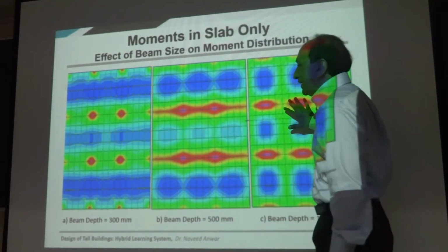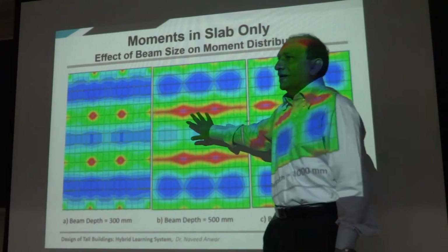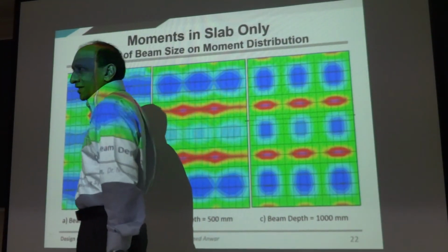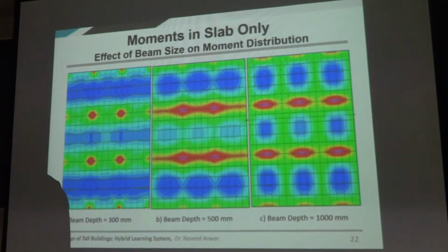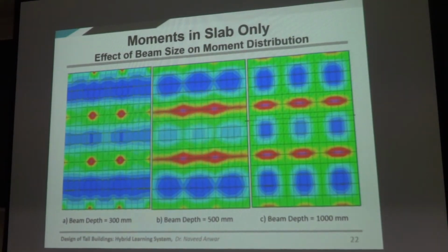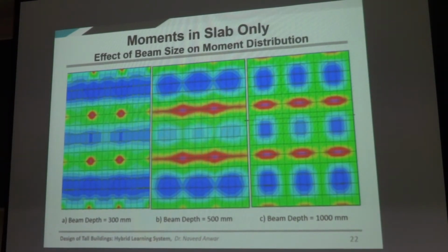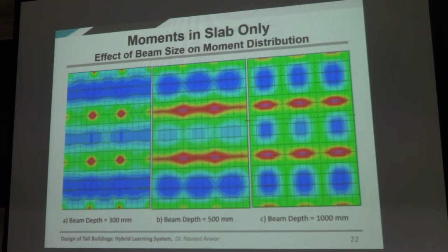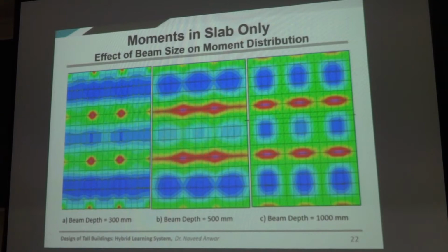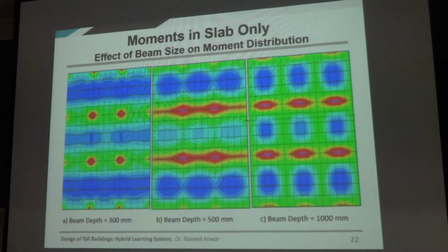So this is the beam comma slab, this is the beam dash slab, now you understand. So when the beams are not stiff enough and they deform with the slab, we call it beam slab. And if the beam is strong enough to act as support for the slab, we call it beam and slab or beam comma slab.